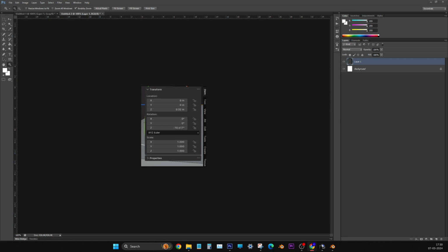View be like that. Now both the vertices are in the same place, but they are still not one vertex. Those two have to become one. How? Go to right side. X-ray. Switch on the X-ray mode. Right side, right, right. Yeah, next. Yeah, that.